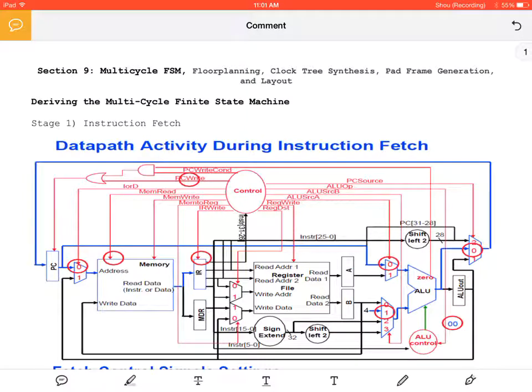As you guys are finding out, CAD tools can throw weird errors where you think, I don't even know why this is doing this. The key thing is, I want to see that you made an honest attempt to do it, and that you made an attempt to troubleshoot. So in your challenges section, let's say you lay out your NAND gate like you're doing in lab 2 right now, and you get, I'm going to use yours as an example, 20 errors and they're all in the NMOS section.